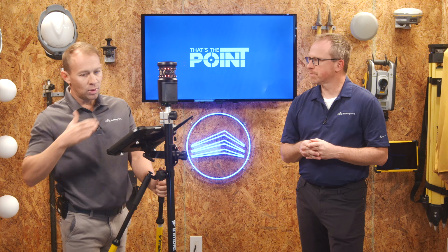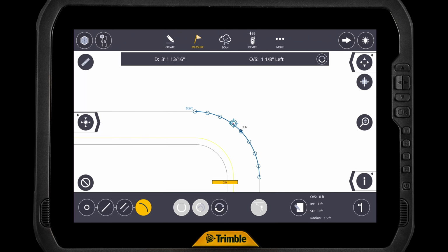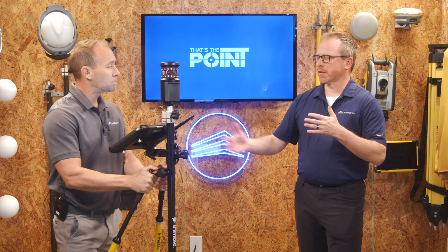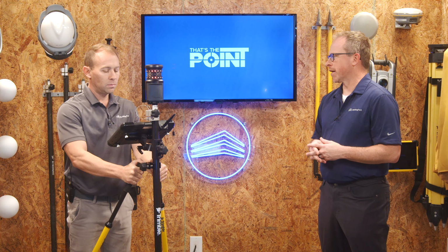I can walk anywhere along that arc, and it's just going to tell me where that arc is in relation to where I'm standing. So, I just stopped here randomly, and it's telling me I'm 2 1/8 left of that arc, so I would need to move back over. It really is a powerful tool, though, if you're just trying to get out there, get a sense of where you are at a job site, doing some minor temp work, stuff like that. Yeah. It's a much quicker way to go out rather than creating points on your own.